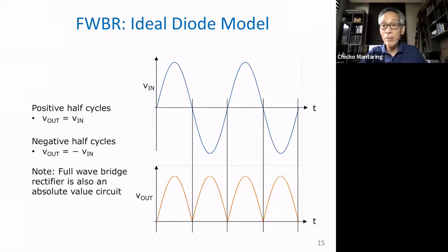So one thing you can put is a full wave bridge rectifier. Because the full wave bridge rectifier, no matter what the polarity of your input, your output will always be of the correct polarity. Okay, so that's one of the practical uses of a full wave bridge rectifier na hindi rectifier yung ginagawa. No? It's more a polarity corrector.